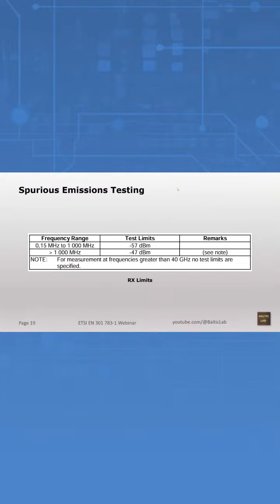And this is a funny thing that I've never seen mentioned anywhere, but it's in the rules. You don't just test for spurious emissions while transmitting, but also while the radio is in receive mode. And I've seen there's plenty of amateur radio operators in the comment sections, and depending on your age, you might remember very simple transceivers from the 40s, 50s. When somebody would tune their radio, the local oscillator would feed through, and you can actually hear that, especially in CW mode, that somebody's local oscillator was running on that frequency. And that's important and often missed.